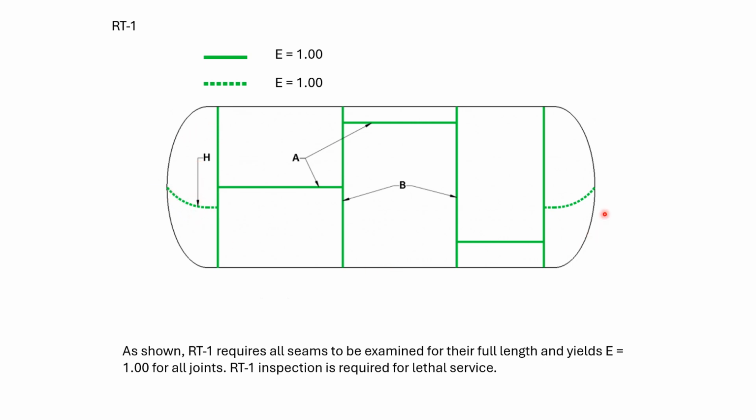The H in the picture indicates that there is no need to do radiography over here, because this joint is normally done in the ground position. Okay, because the welder has very good welding efficiency when welding in the ground position. That is what we call 1G welding. That is the bottom horizontal welding, where the plate is placed at the bottom and he is welding. So normally we don't